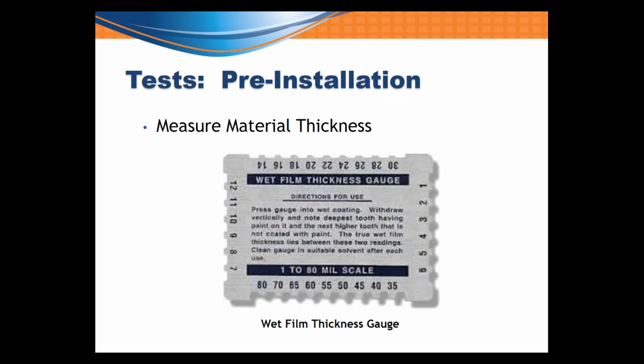Then you're also going to measure the material thickness. Markings with a required wet film thickness of 80 mils or less should be measured with a wet film thickness gauge. Prior to installation, a contractor should place a test strip without the glass beads at a calibrated travel speed, and the wet film thickness should be measured on the test strip.